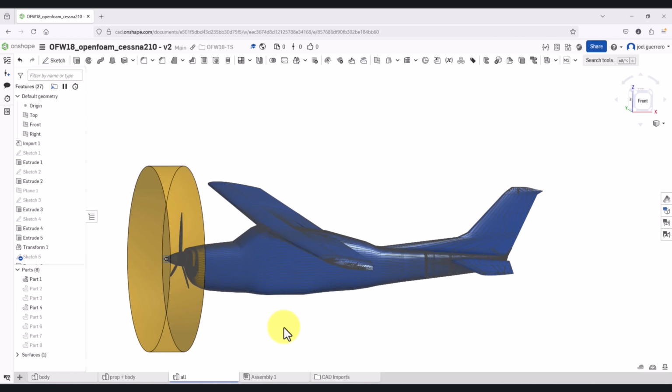In this video what we're going to do is add this region. So we have the same domain, refinement region. You can add all the refinement options, there is no problem, but what is important now is that we add this region here. This is to separate our domain. So we're going to have, let's say, a subdomain contained within this cylinder, and here we have the propeller. And the idea is that now in this region we can put things into motion, sliding meshes, or we can add a source there, so the MRF approach. So this is what we're going to do.